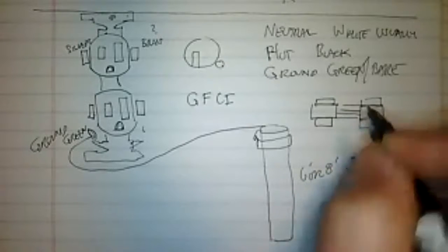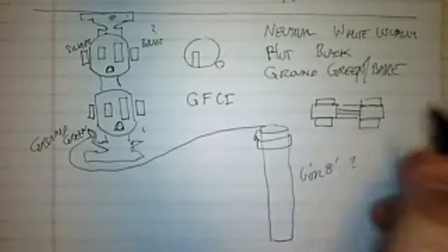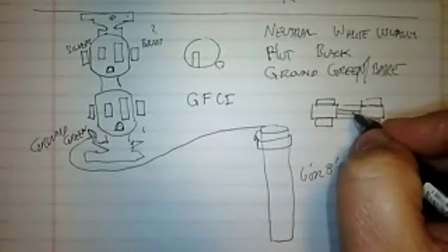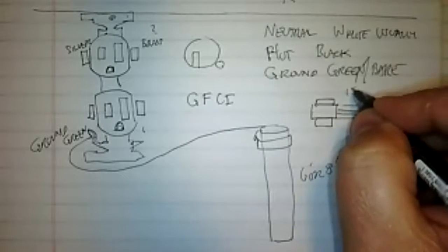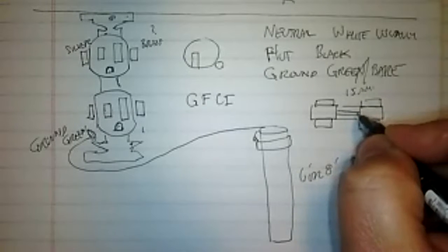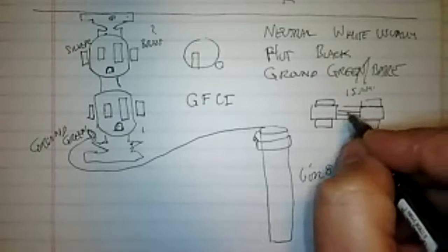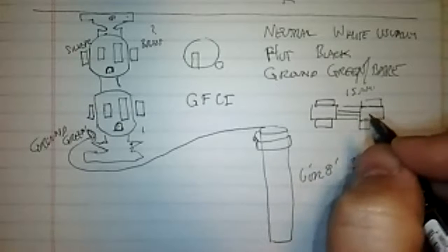That ribbon of metal has a certain thickness and a certain width. And the people that make the fuse have discovered that if that current exceeds, say, 15 amps, then that metal ribbon will melt in two, and that opens the circuit and causes the current to stop flowing.